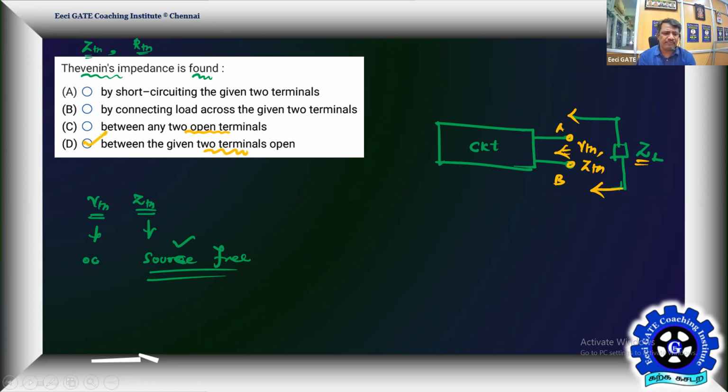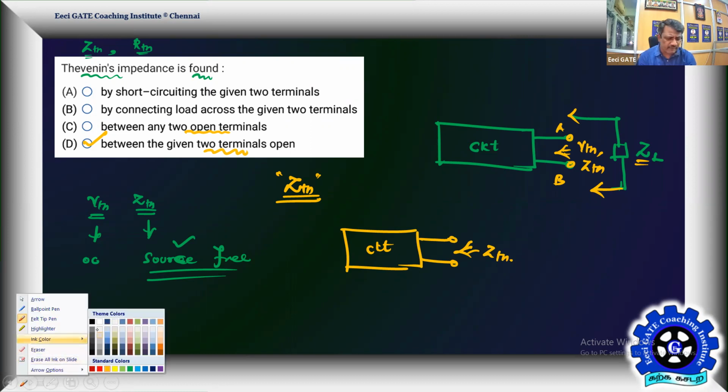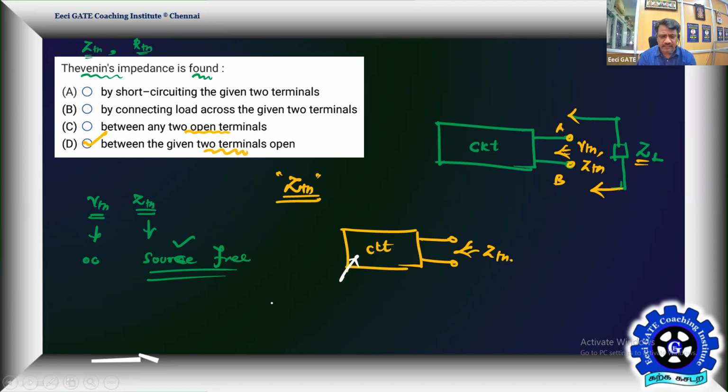A simple problem talking about impedance, Thevenin's impedance. That's easy. Another important point I want to convey here is that this is a circuit, so you can find the impedance of a circuit. You are looking for this Thevenin impedance, so you can happily apply a potential, but for that first you have to switch off all the sources in the given circuit. Switch off them, then apply a known potential. This will help you.